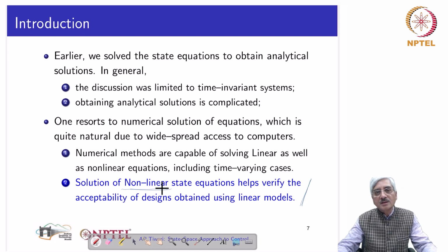Based on the linear model, generally we design a controller or a state estimator, and then the controller, along with its parameters and structure, is to be implemented back on the nonlinear plant or the system. Similarly, the nonlinear states are to be estimated using an estimator which is essentially a linear estimator.